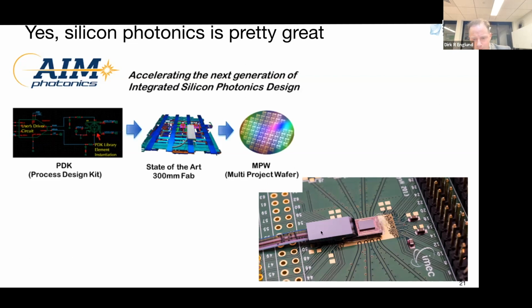Here you see the fibers, and they're in this fiber V-groove array. And this here is a prism. So light from the photonic circuit couples out through a grating coupler and then reflects off of this smooth surface into the fiber core. So this is a vertical grating coupler via a prism fiber coupler. And then light comes in and out via these waveguide circuits. This is a nice way to keep the whole thing a bit more compact, and it's easier for packaging.